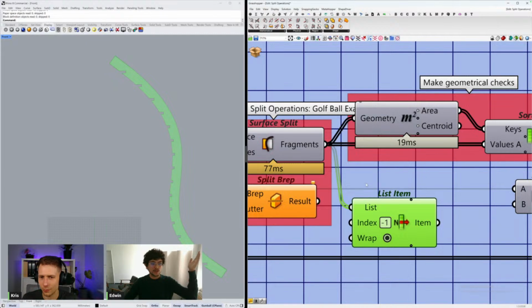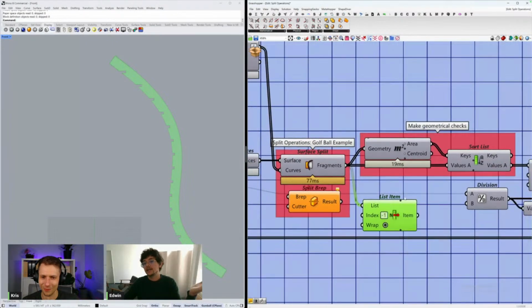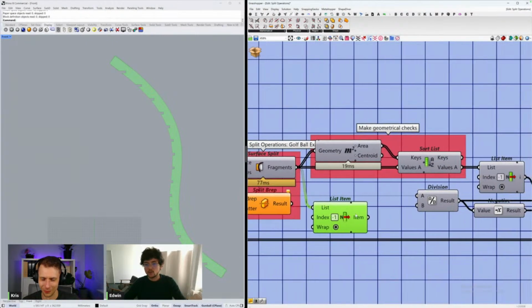oops, my model doesn't work when I upload it in ShapeDiver. Well, maybe because you created it in Rhino 5 and ShapeDiver is in Rhino 6 or Rhino 7. And then, of course, if you try that on your local machine, it will be exactly the same. You will have the same problems because the different versions do it in different ways.